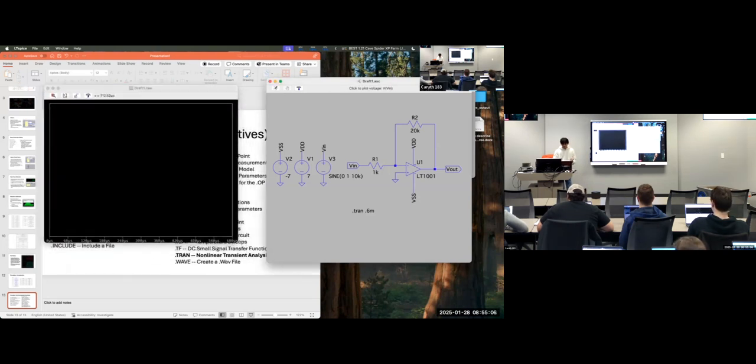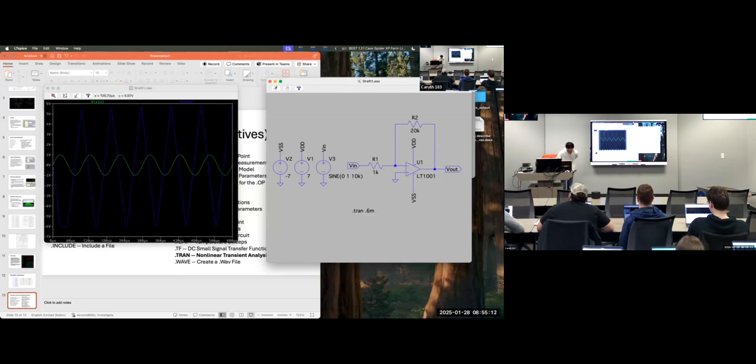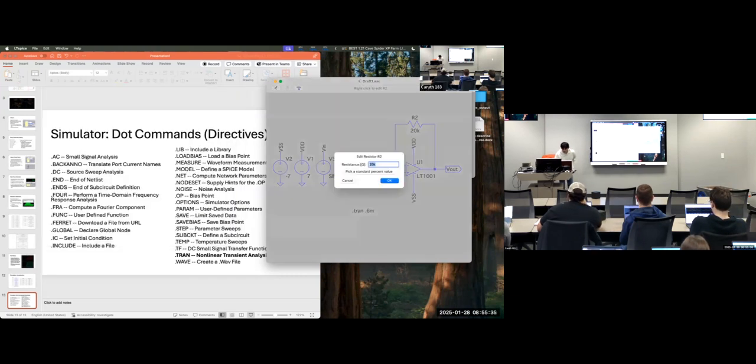That would be analog. So the in looks pretty normal, and the out, look at that. We see 6 and -6. And then we also see this weird phase shift, they're not perfectly opposing each other. And we see some clipping on it. So you're right. Like I said, in lab, if there are questions that you're uncertain of, throw it in SPICE, mess around with it, have fun with it. We can also do other interesting stuff. So one more thing I'll do is set this back to 5.